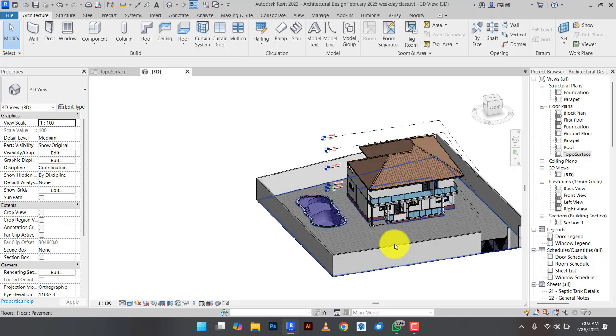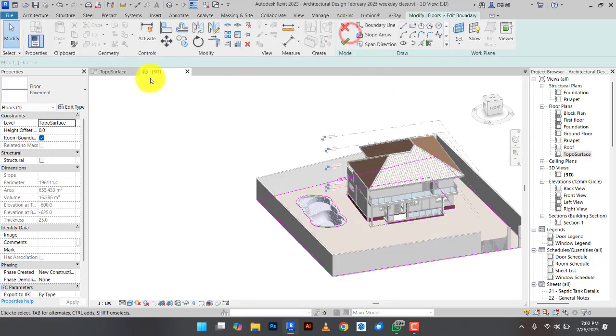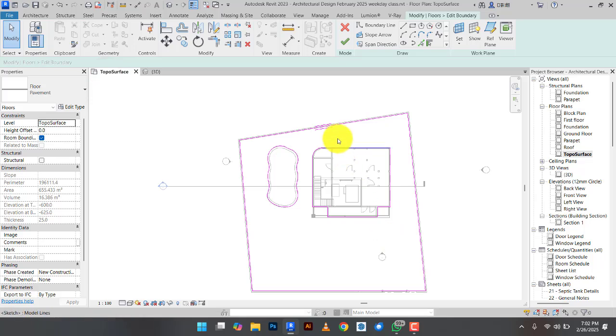And so, any side you don't want to pave, you take it out of the selection. So maybe you want to have green around the wall. If you want to have that, it means that you click on the topo, click on edit boundary, go back to your topo surface. Then it means you have to remove this from the wall.